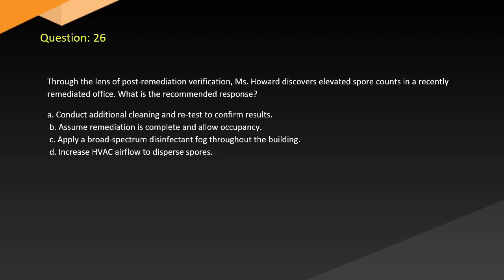Question 26. During post-remediation verification, Ms. Ramirez discovers elevated spore counts in a recently remediated office. What is the recommended response? A. Conduct additional cleaning and retest to confirm results. B. Assume remediation is complete and allow occupancy. C. Apply a broad-spectrum disinfectant fog throughout the building. D. Increase HVAC airflow to disperse spores.